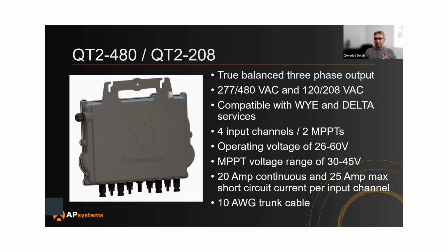So Q2T inverters attach to a 10 gauge trunk cable. That's something we supply. The trunk cable has connectors already, so you plug them directly into the trunk cable. Again, the option is 10 gauge. For the DS3 series, you can get 12 gauge or 10, but for the Q22s, we go with 10 gauge only.